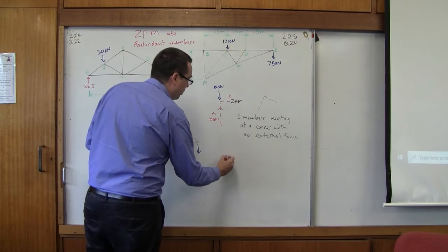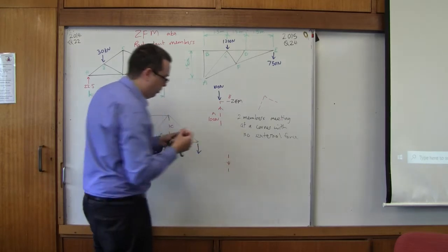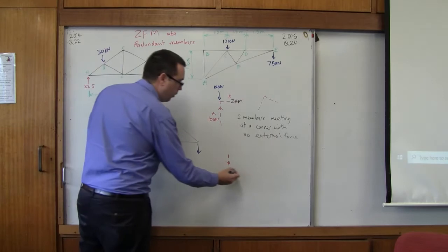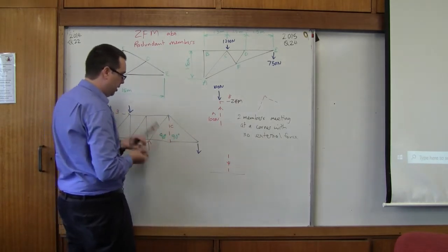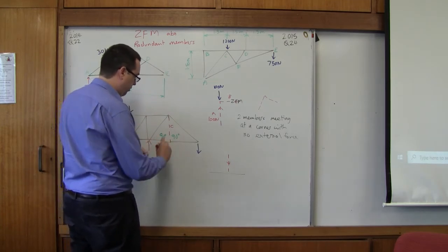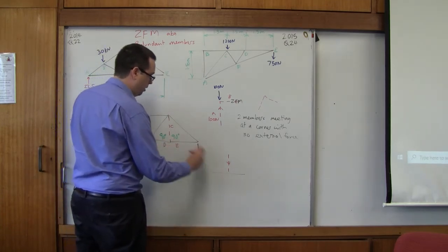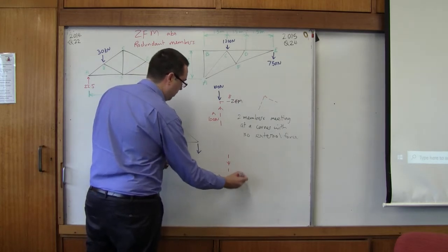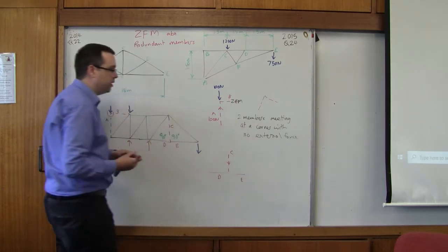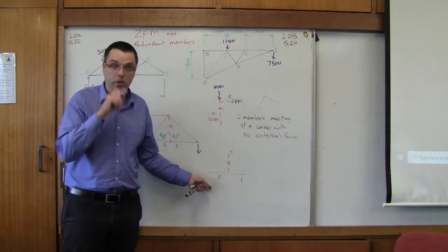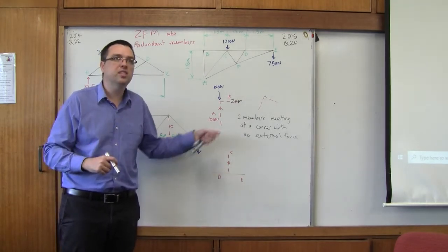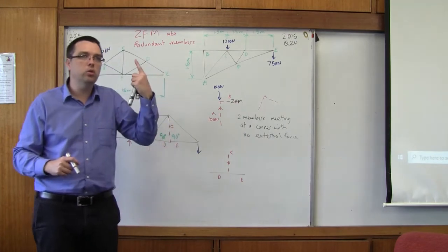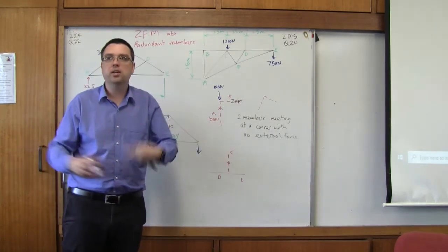If we look at that joint, if we draw it out here, let's assume that C is going down. We have these two members here, I'll label them D and E. If I have D and E, and this is C, what we can see is that D has no vertical component, E has no vertical component. So because they have no vertical component, if C has any amount of vertical component, even 1 Newton, it's going to push this joint down and break it.